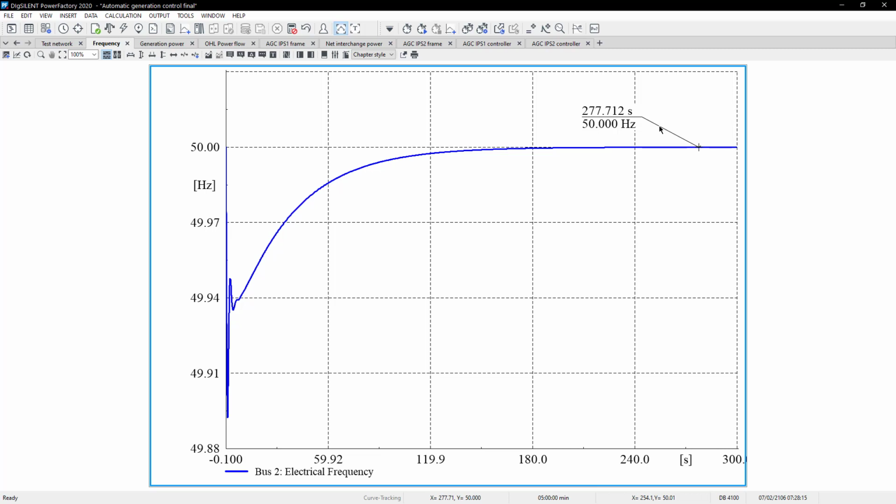Well, because first I want to teach you the basic idea of the AGC, and to show you that the AGC is working. The first simulation was without AGC. You can see that the frequency is still below the rated frequency. Then I activate the composite model, that is the formal name, and all the DSL are working. And now we have the full AGC action, and you can see how the frequency recovers, okay?